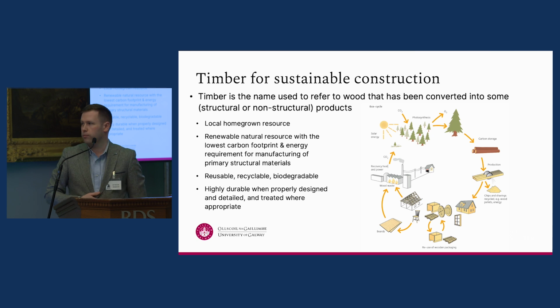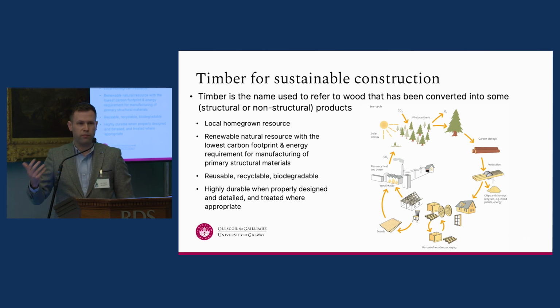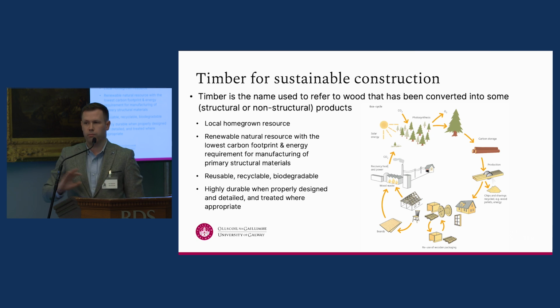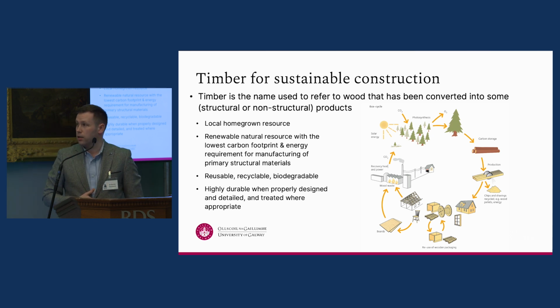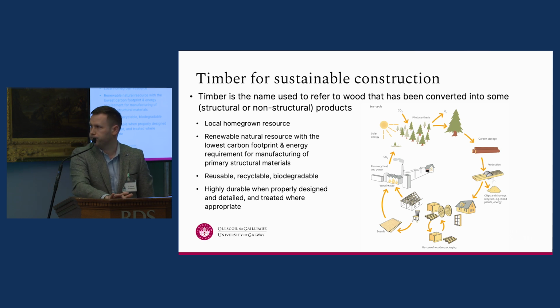One of the concerns with timber I hear a lot tends to relate to fire, but from our perspective, we're generally not as concerned about fire as we are about water. Fire and timber and steel and concrete is very well understood, but moisture is an area that needs to be taken care of. So that's where correct design and detailing comes in. So understand your material and how you should use it.